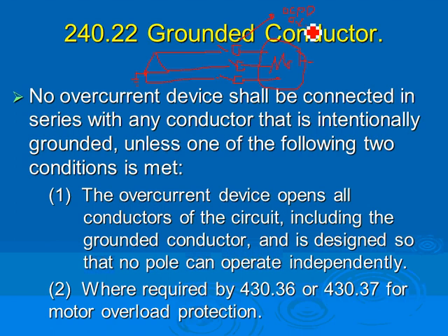But what's wrong with this? Now you've got a grounded system, so you lost that advantage of an ungrounded system, which is that a ground fault will not trip you. Against this, a ground fault will trip you. A ground fault here, would a ground fault here trip you? No. It has to be on phase A or C to trip you.